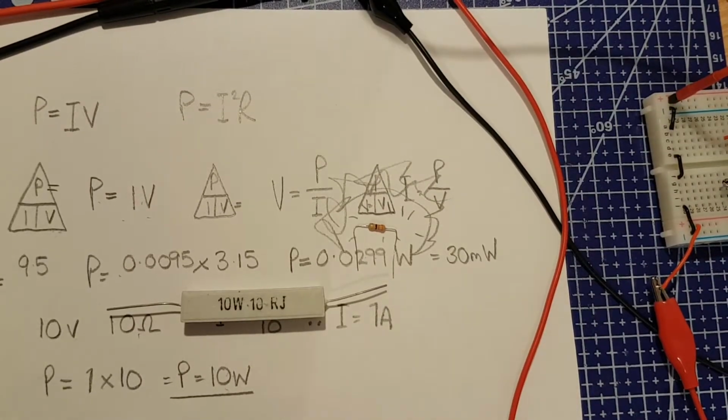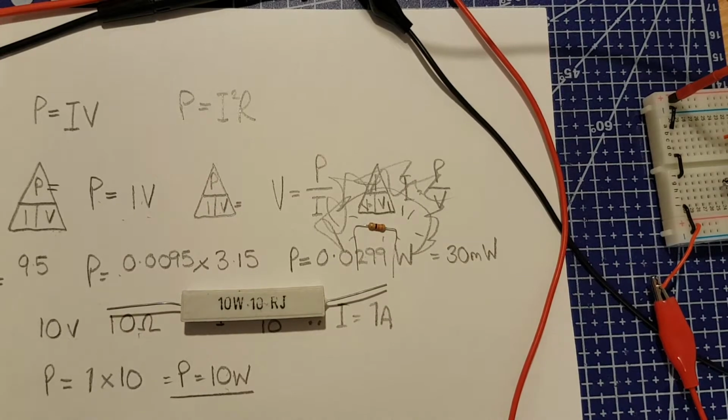So this concludes our episode on Ohm's Law. Have a little practice, messing around with a few values, and try it on paper, test it on your breadboard with your multimeter. Just be mindful of the power that you're putting through the resistors, like I said. Hopefully this will give you a better insight into making your future breadboard circuits.